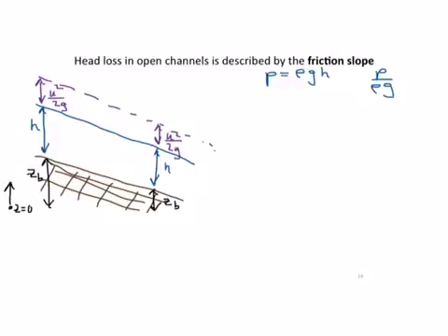And then the total head at this point looks like it would decrease as you go from point 1 over here to point 2 down here. But we know that's not the case. Total head has to be conserved along streamlines, and so we actually need to add another term to account for the loss in head due to friction, and this is our head loss term. So this line here represents our total head, which is conserved from upstream to downstream, and the distance between the sum of the pressure head, the velocity head, and the elevation head, and the total head is equal to the head loss.